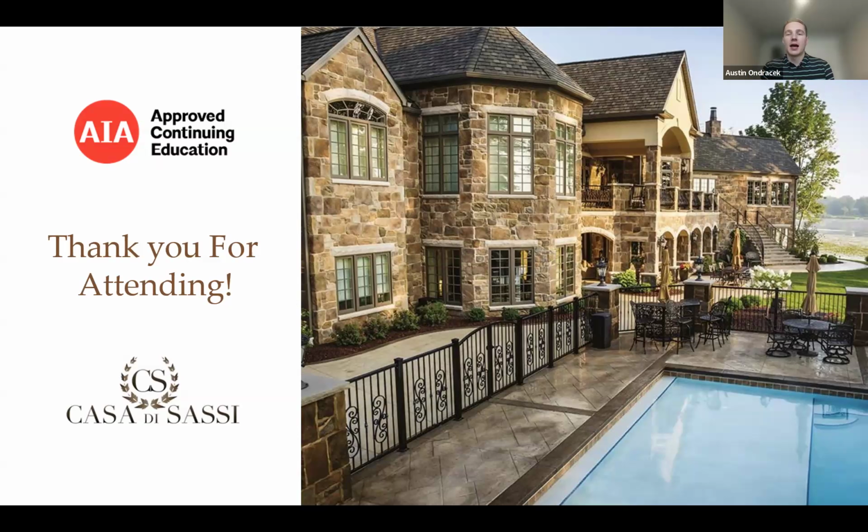Yeah, absolutely. I wish I had that video. I was watching it the other day. A water resistant barrier is something you will always have, and I think you should always have. You should always have probably 2 layers of it, if not bare minimum one. The rain screen is something that would go on after the water barrier. So, substrate, water barrier, and then the rain screen is an added measure.